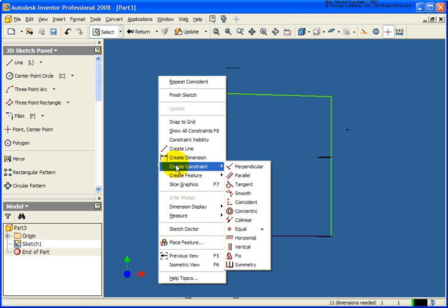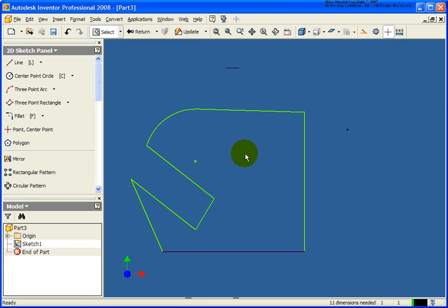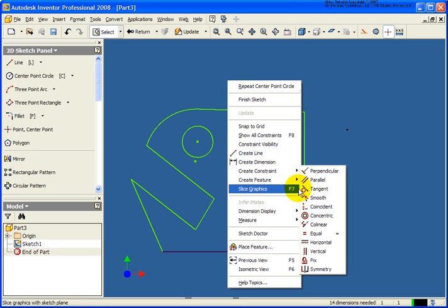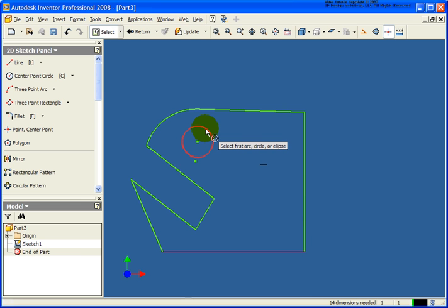And let's take a look at the next constraint, and it's going to be concentric. In this case, I'm going to draw in an arc, or I'm sorry, a circle. And if I go back here and reselect the concentric option, selecting on the arc and the circle, the order does not matter. They will be concentric to one another. Of course, in this case, when I was drawing that, I simply could have selected the center point of that arc for the center point of my circle.